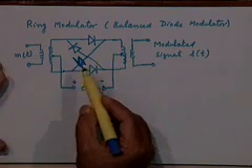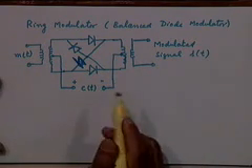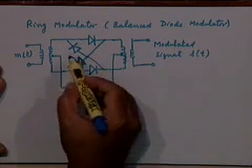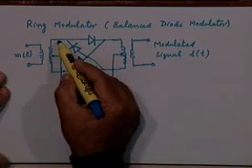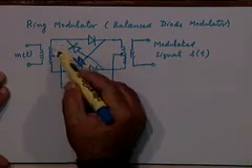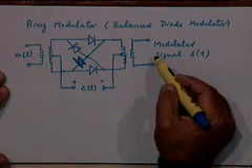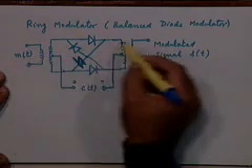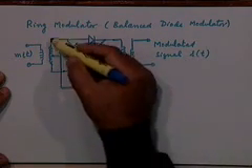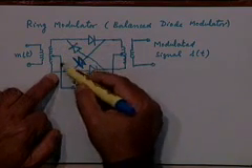So we are assuming that the impedance offered by these diodes at the carrier frequency is very small, right. Similarly, when these two diodes are conducting, basically what you are going to get is this voltage, which is a sum of once again the carrier voltage and the input voltage, appears across this, and therefore across the output directly. In fact, more or less you can say that M of t directly appears in this case, because C of t is actually balanced out, right. There is no net carrier applied from here to here, as you can convince yourself.